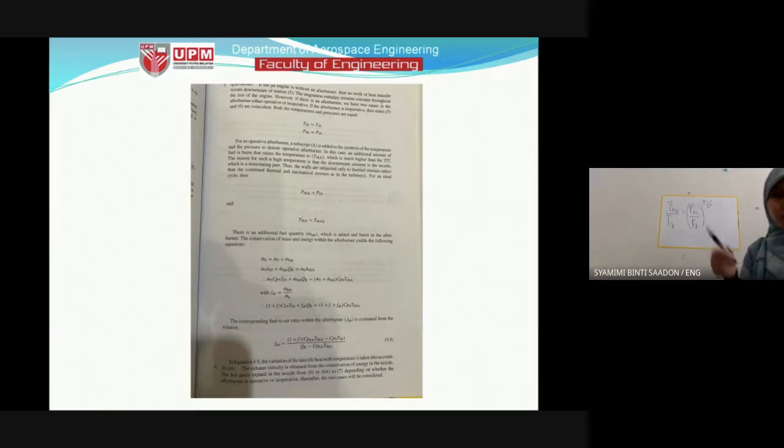It is an unchoked nozzle, remember, unchoked nozzle. So we assume that the exit pressure, which is P7, is the same as the ambient pressure. The ambient pressure is 32 kilopascal. So P7, the exit pressure, equals to ambient pressure because it is an unchoked nozzle. And T total 6 just now is 1106 Kelvin, which equals to TO5.